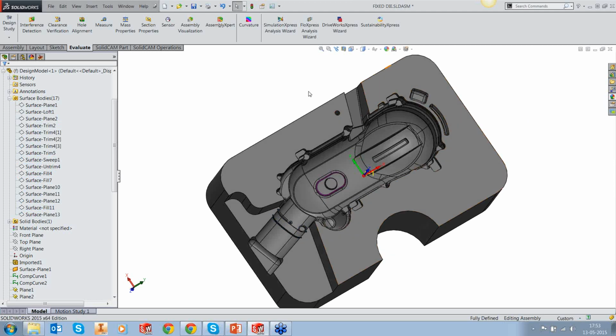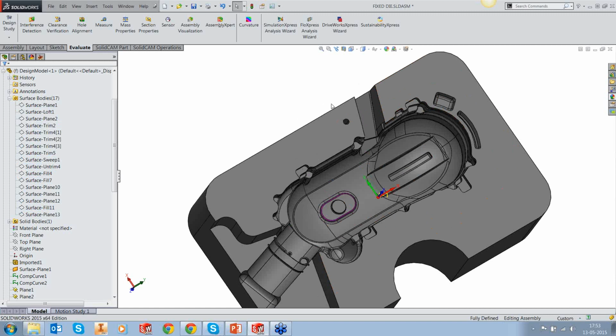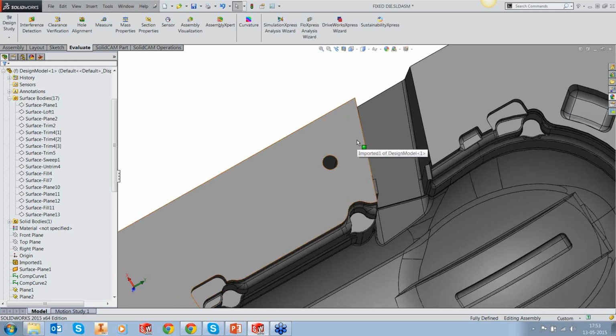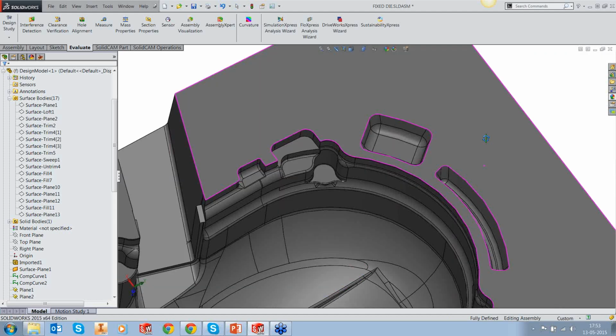For example, I have a hole. It has no reason to be machined in 3D, so this must be off. This has to be done in drilling and then boring, or drilling and reaming. Then there are two what we call overflows, because this is a die casting die. Again, they are very small.